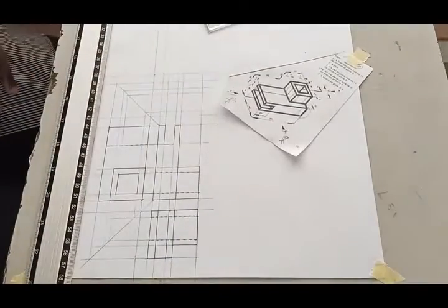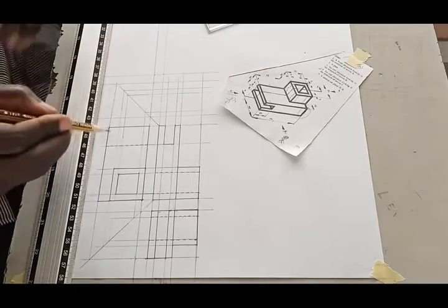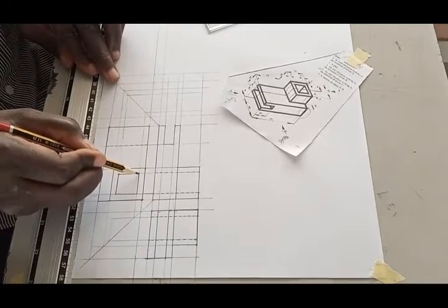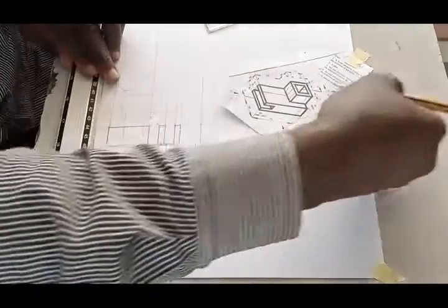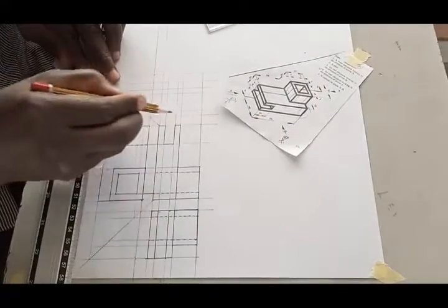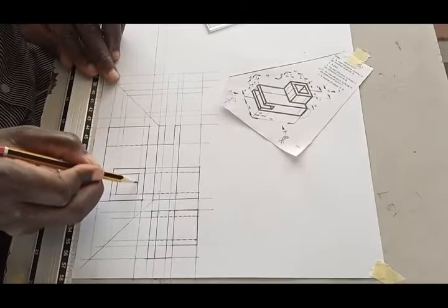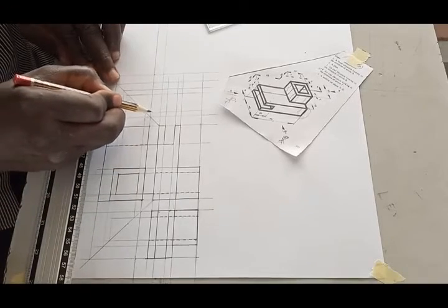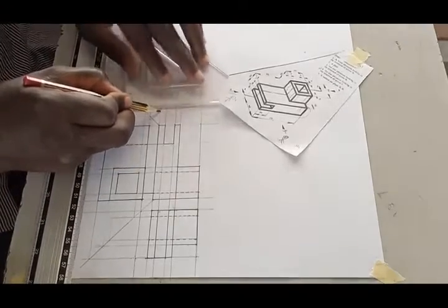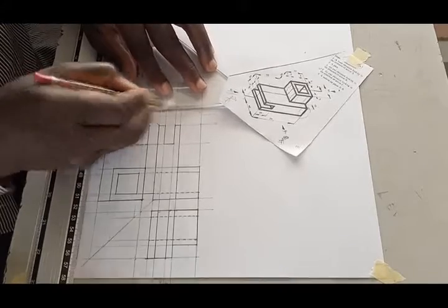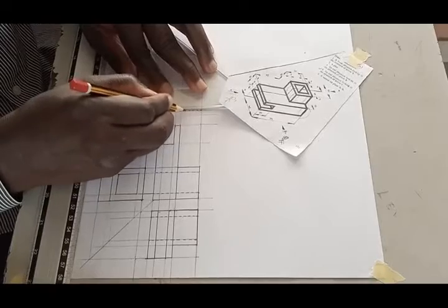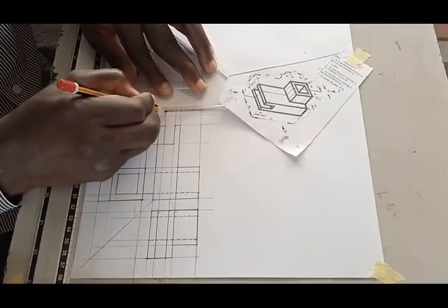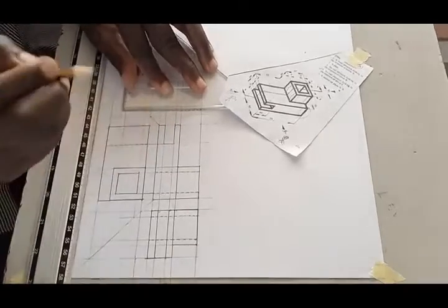and vertically upward. Now you can see that this box, the internal part of the box, is this one, which is, we are viewing it from here, which will be hidden line. Remember, this is the line going like this all through, so you can just indicate that with hidden line, because you cannot see it, but you know that the edge is there all the way to the bottom.